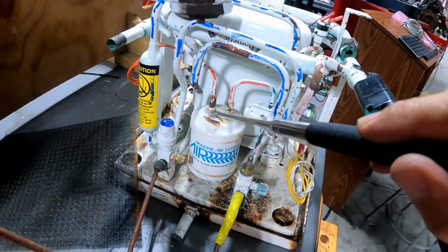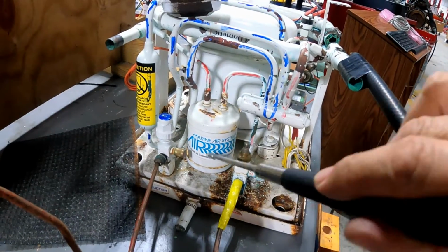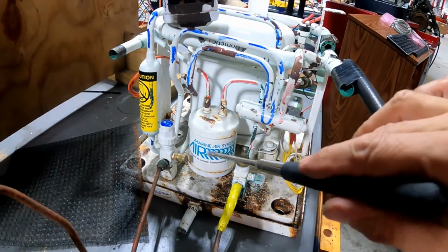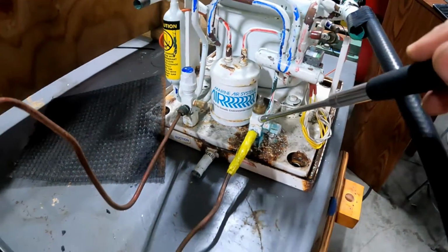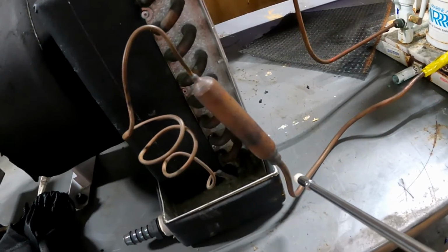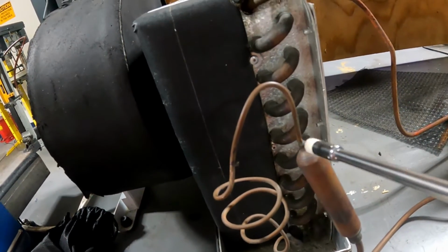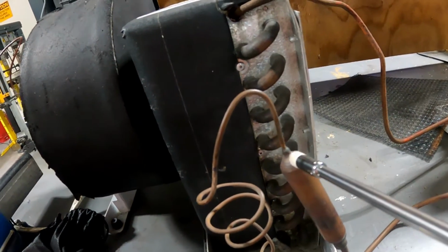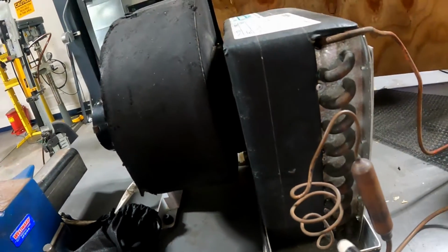The refrigerant enters over there, in the bottom, and the hygroscopic substance absorbs humidity, absorbs moisture. For that reason, the name of that element is receiver dryer, to accumulate moisture over there. And after that, the refrigerant at high pressure continues and enters the expansion valve. Look at the reduction in diameter. This is the original diameter, this is the output diameter. At this moment, the pressure and the temperature drop dramatically, and after that continues the capillary pipe. This is the expansion valve.